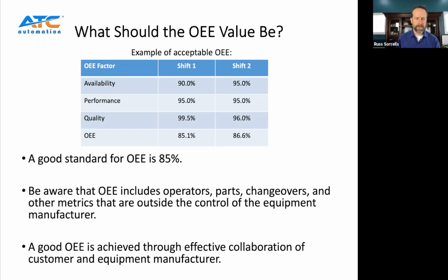It seems, Bob, and correct me if I'm wrong here, that if you were going to measure OEE, you would want 6 months, 8 months, 10 months, 12 months of operation on your brand new piece of equipment to really understand, because by then your operators are trained, your product flow into the equipment should be sufficient, and any bugs ideally worked out of the equipment, so that it doesn't have unnecessary stoppage because of a part.